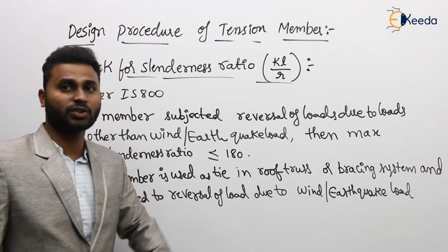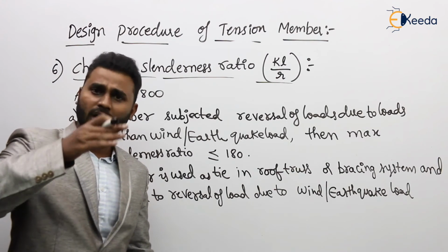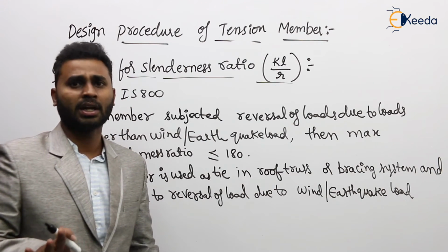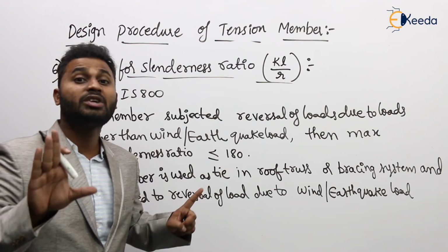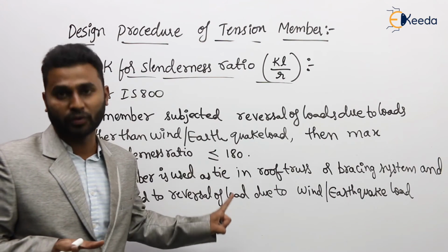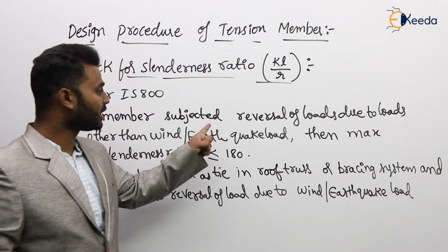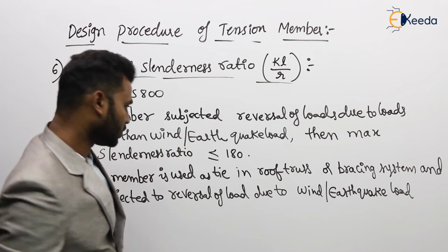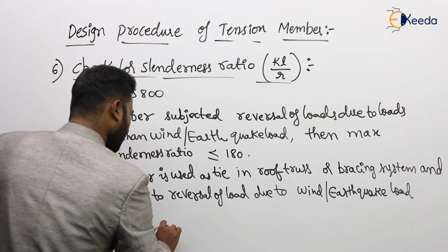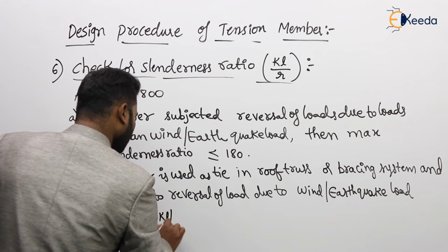So in a roof truss also we have upper chord and lower chord members. Agree or not? Now this provision is for members and bottom chord members of a roof truss. For both the members, this is the provision. But the earlier one is only for members in a bridge truss. So now, in this case, L by r or KL by r minimum.